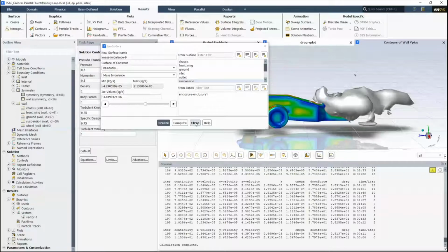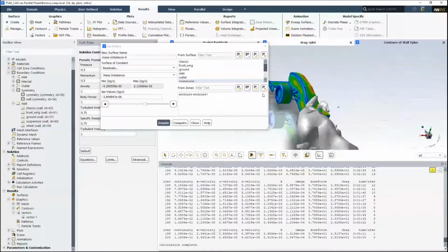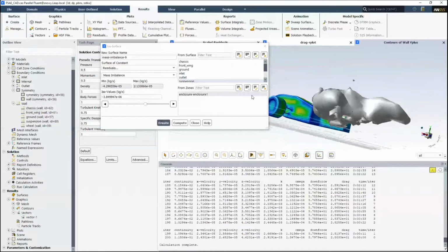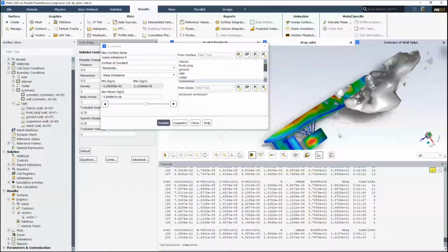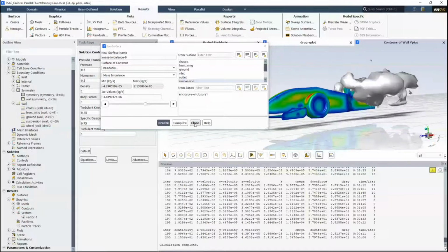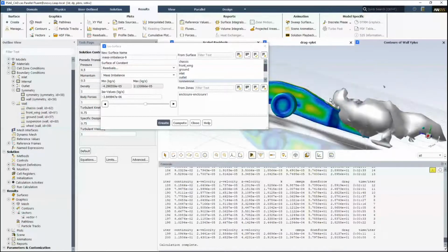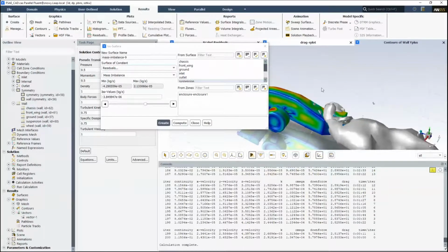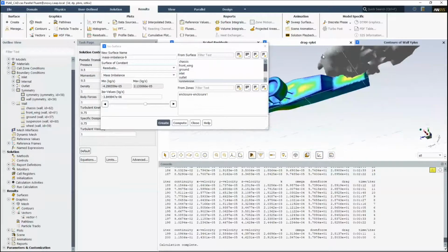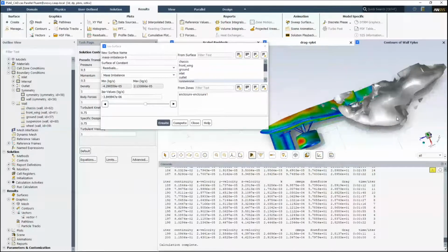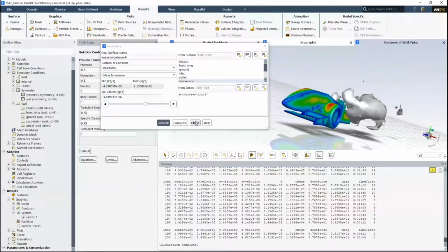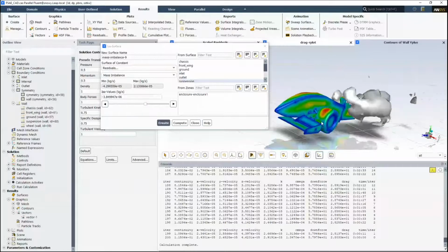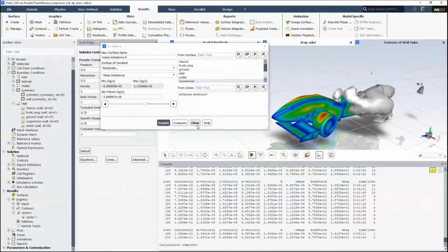Okay, so that's using these tools to try and get an understanding of why maybe we're not converging. That's one post-processing method. One thing we might do here is ignore it, or we might just change our under relaxation factors. There's a few things we would do. We would just have to run some tests and continue to solve until we were happy enough with the result.